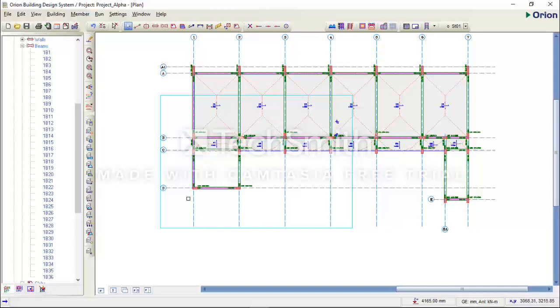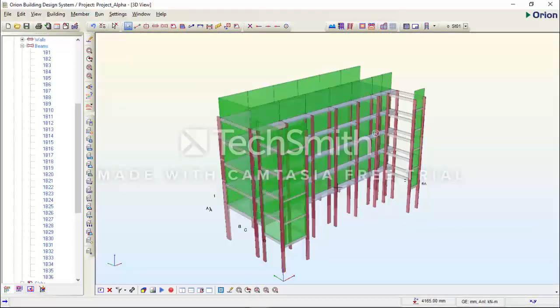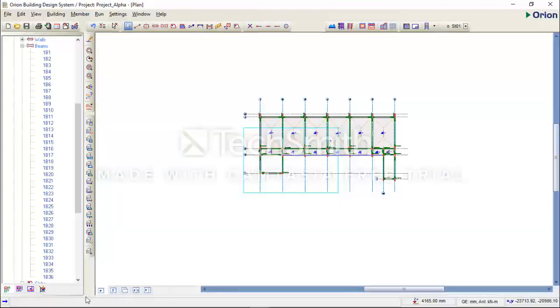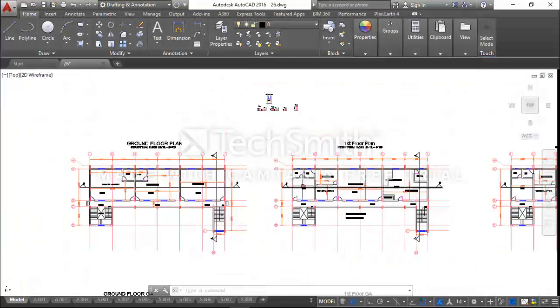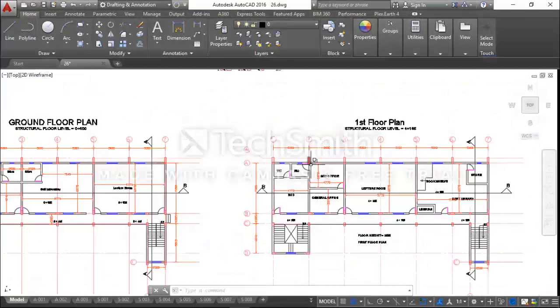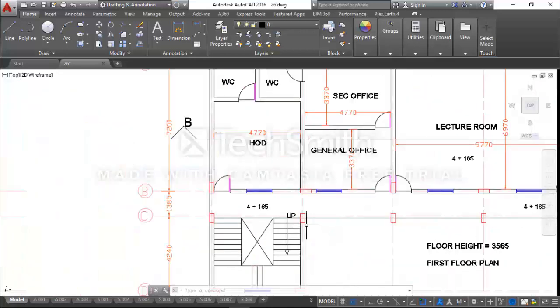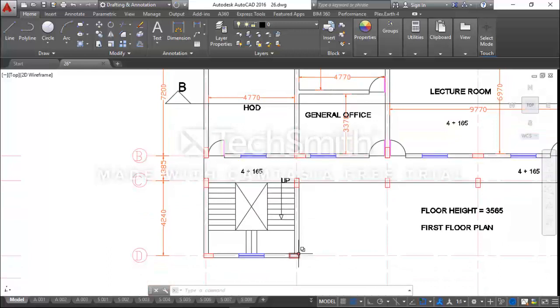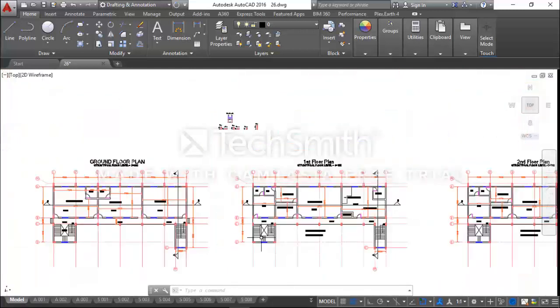So I'll specify the wall load along line 1. Along line 2, what do we have? I'll go to my AutoCAD drawing. Along line 2, we have wall load from A to B and also from C to D. But beam C to D is a staircase load. So I'll need to determine the height of the wall on the beam between C and D.